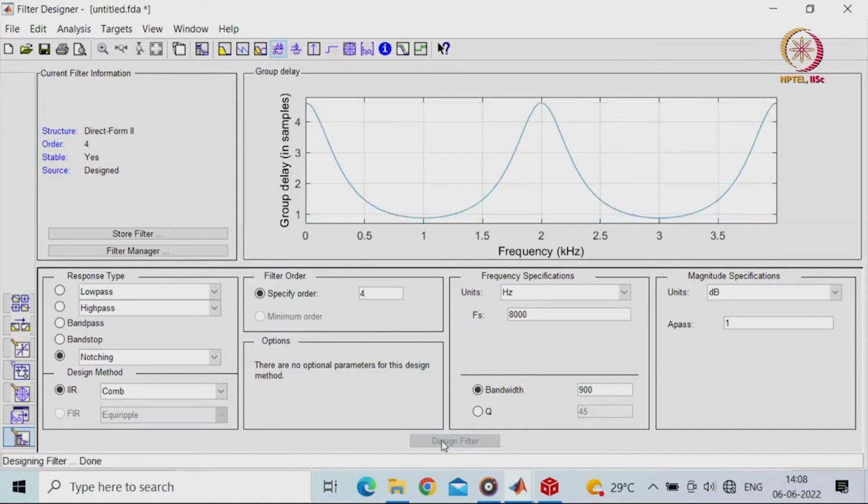What is happening here? You can see that approximately 900 times 3 is going to be your 2700. So, I can design this, and this is my passband region that I will be selecting, and there is going to be a notch here and a stop band happening here. So, I can use this to take my filter coefficients and then run it also, fine. Or you can take them individually and put both together, so you run one filter after the other, fine.